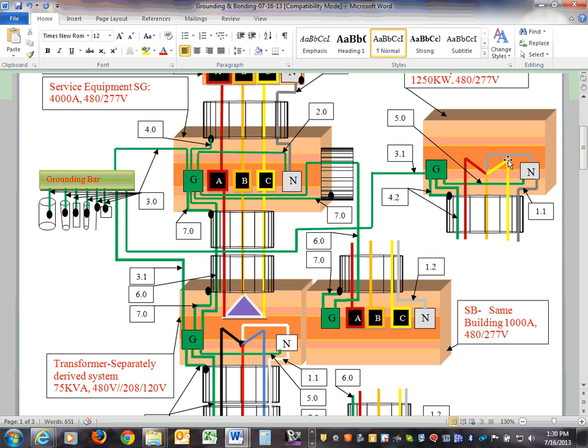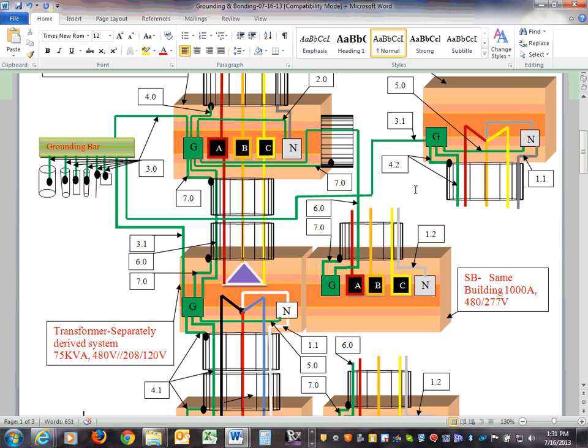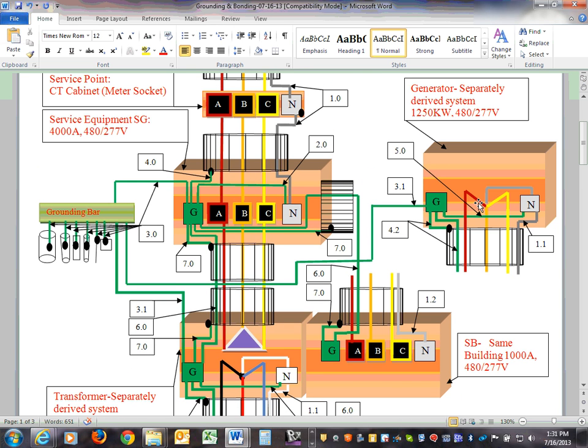Any comments, guys, about these 4 scenarios that I ran for you from this switchgear here? I believe these will cover everything in grounding and bonding, except DC grounding and bonding is not covered here, and high voltage. Other than DC and high voltage, if you have a 600 volt DC line, or if you have a 13.8 system, these are not in this scenario. Other than these, everything basically is covered, related to AC 600 volt or less. Any comments, guys, before I go into each one of these scenarios?